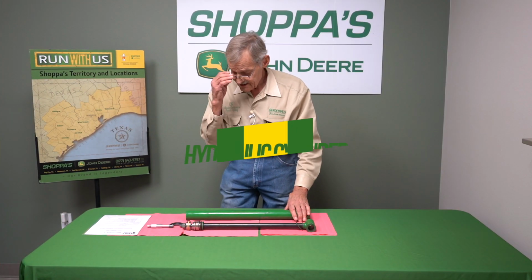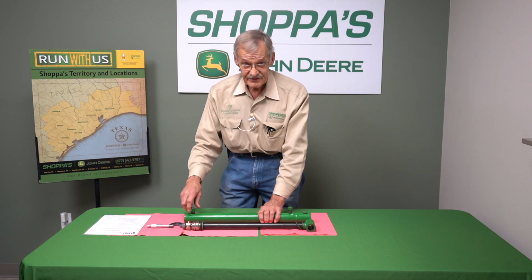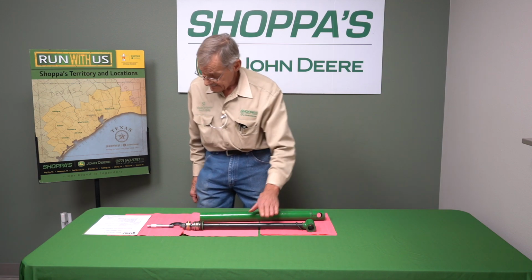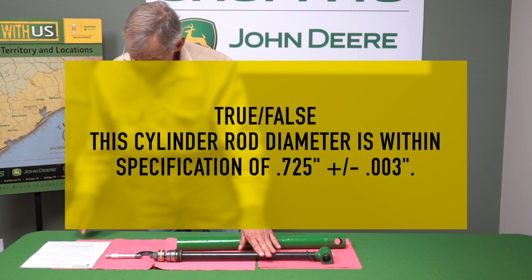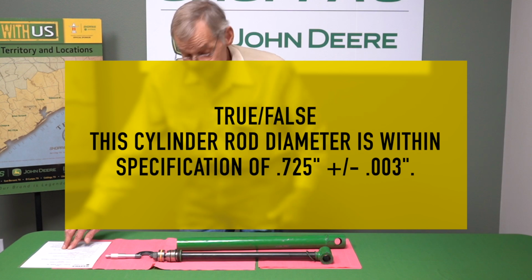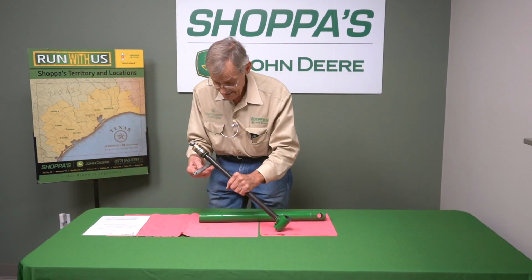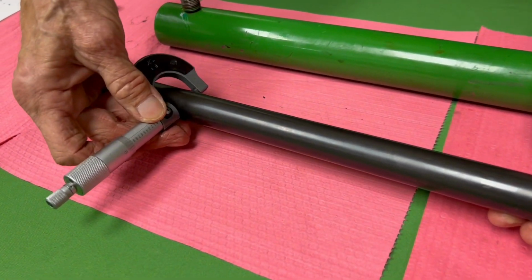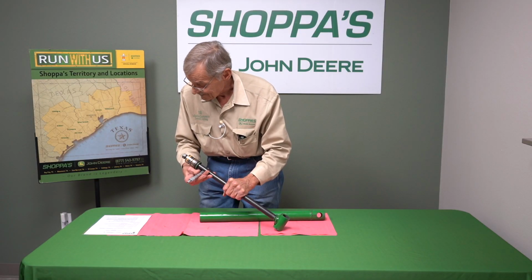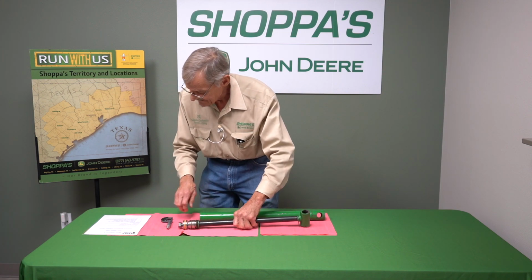Okay, our next component is a hydraulic cylinder. Very common, multiple applications throughout many industries. Okay, our first question or statement: this cylinder rod is within specification of 0.725 plus or minus 3/1000 of an inch. Okay, miking it, we are well over 950 thousandths. So that's false. It is not within that specification.